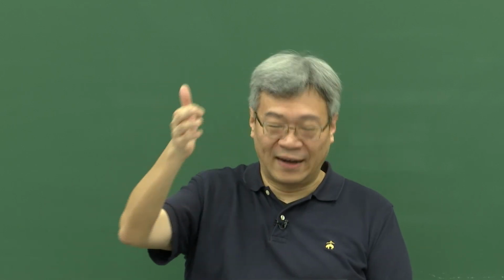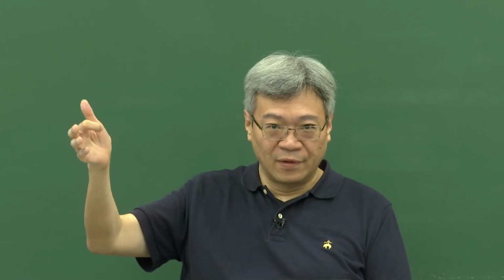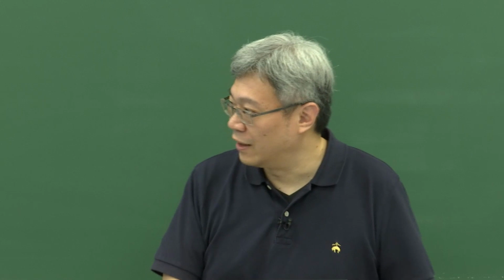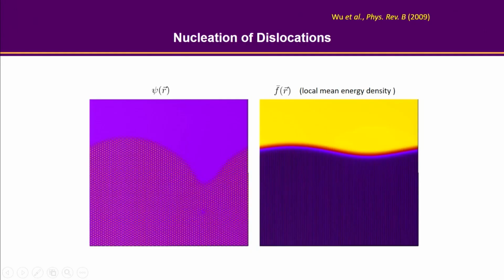By forming that, you are releasing the elastic energy above that dislocation. And the dislocation is going to come downwards, because once it goes by, it reduces the number of lattice planes above. That's a very efficient way for the system to get rid of the elastic energy.